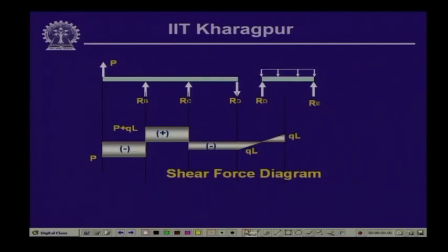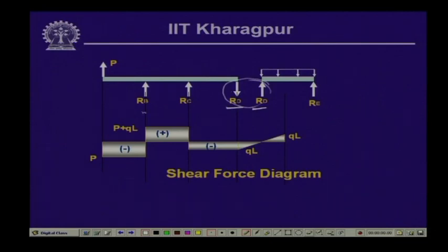Now, this is the diagram plotted, but you see that this beam has been split at the articulation, and we have introduced one reactive force R d over here. Please note, these two forces are balancing in nature. That means one beam is getting supported over the other and transferring the shear force here. So, it can resist the shear force, but it rotates when it comes to bending. Now, the uniformly distributed load acting over here is Q. This is of length 2L and all these segmental lengths are L.